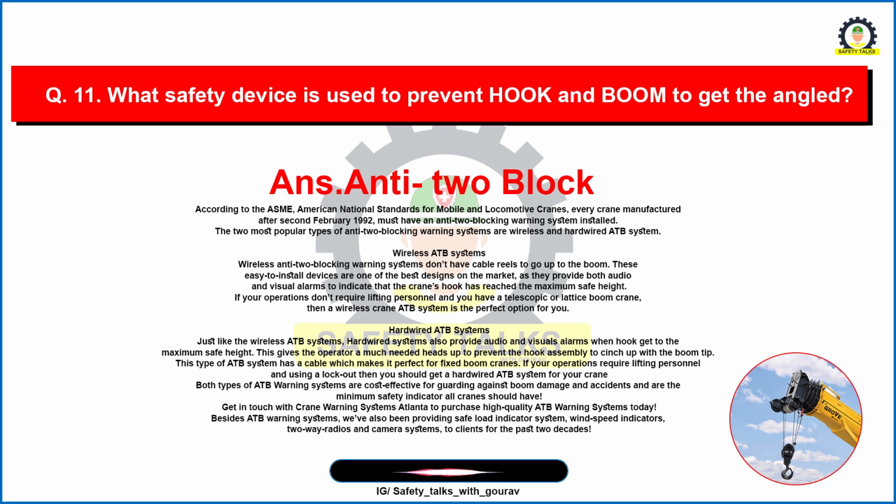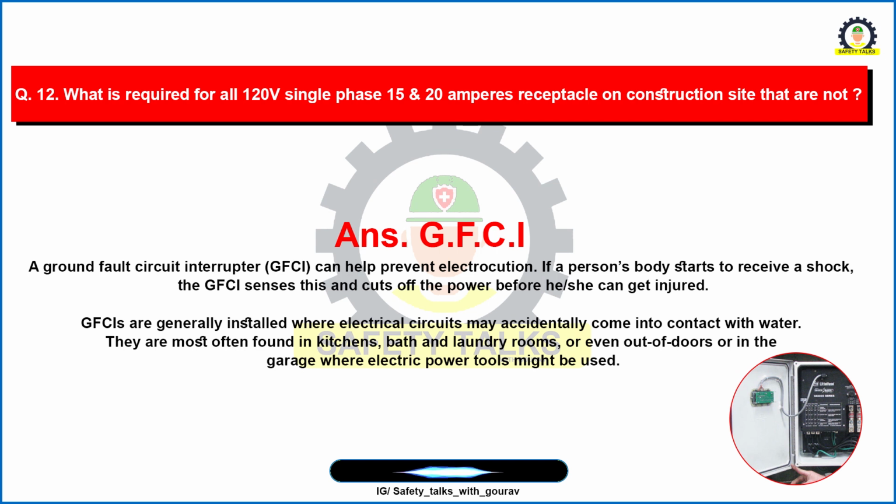Okay, so now let's move on to the next question. Next question goes like, what is required for all 120 volt single phase 15 and 20 ampere receptacles on construction sites that are not part of the permanent wiring? So the answer will be GFCI. GFCI stands for ground fault circuit interrupter.